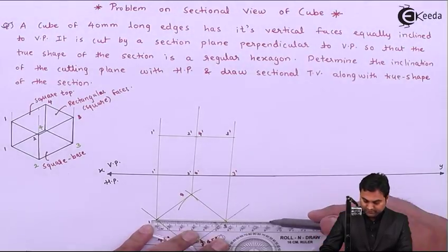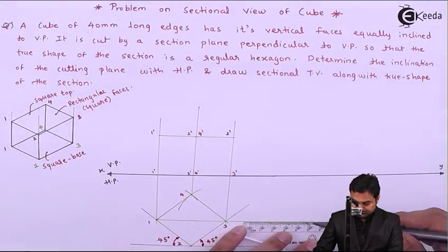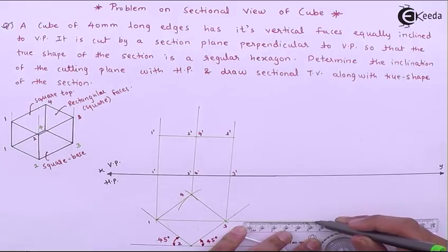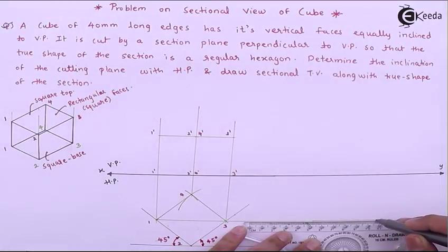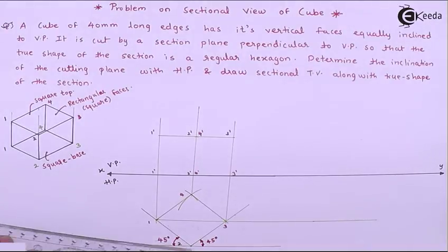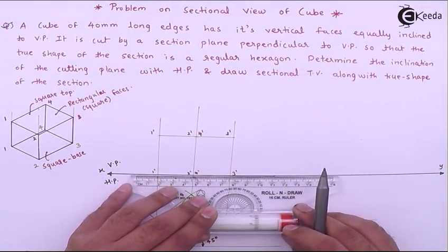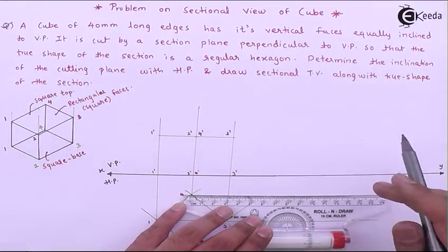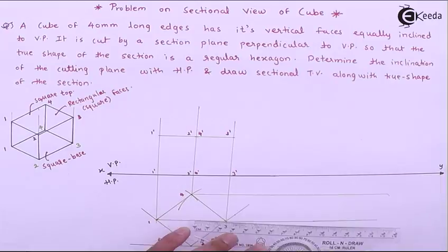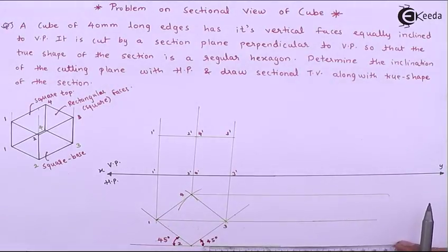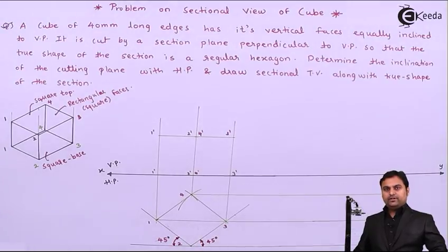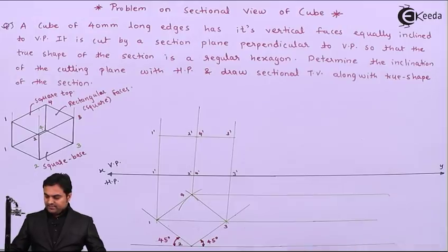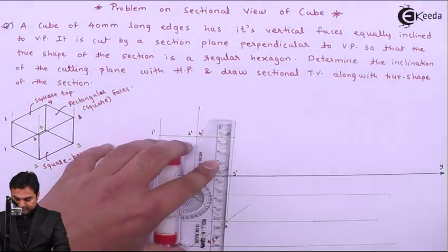From 1 and 3, drawing a light horizontal line. Then similarly projecting point 4 with a light horizontal line, point 2 with a light horizontal line, then drawing a vertical line. Next, as I have projected these points, here I will draw the vertical line.